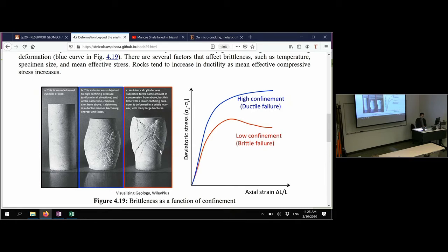When you start increasing the level of confining pressure, or to have more stress in all directions, your rock is going to start to fail differently. And I hope that you remember from your triaxial test, especially if you did 300 or 500 psi, your fracture was a lot more defined than the one for the unconfined compression strength.